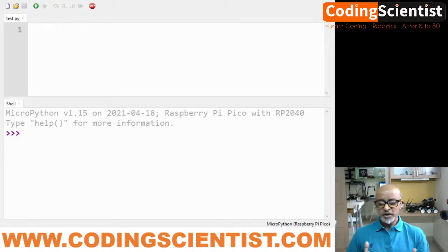So basically machine pin, the pin objects are commonly associated with a physical pin, right? Physical pin of the microcontroller, which can basically drive an output voltage and read an input voltage. So what does that mean? You are going to write a Python code, a MicroPython code, to send an output voltage to any specific pin, the GPIO pins. Out of 40 pins there are 25 pins, and then read the input voltage you are receiving either through a sensor or motors you want to drive, or anything else, right? So that's how this entire communication between the microcontroller and the sensors works through MicroPython.